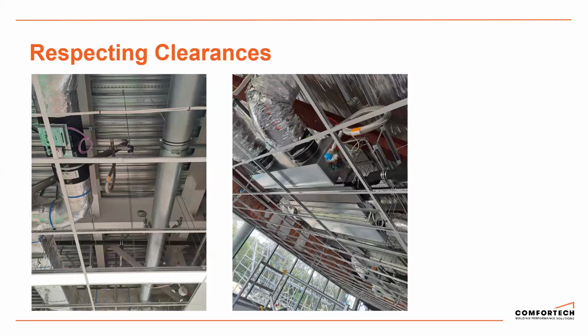So just continuing on with clearances, realise that service congestion is a real issue on site. In particular, concentrated areas like corridors, where we often see them being used as service highways. We chuck all the services down the corridors to get them out of the way. So a proactive approach and good coordination can help mitigate issues and delays on site.